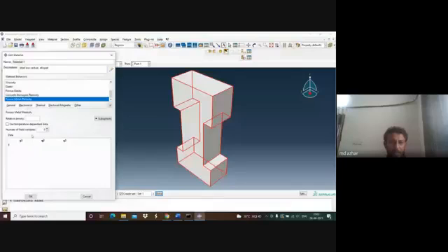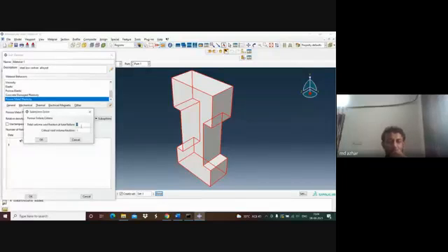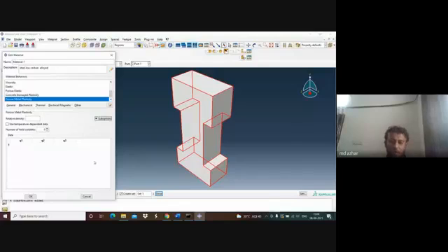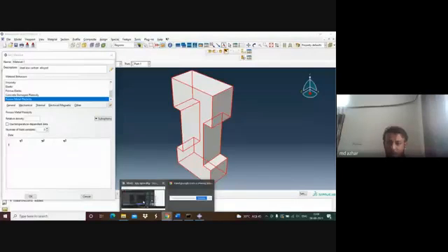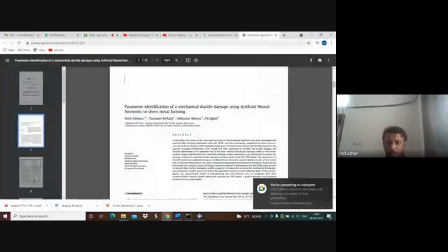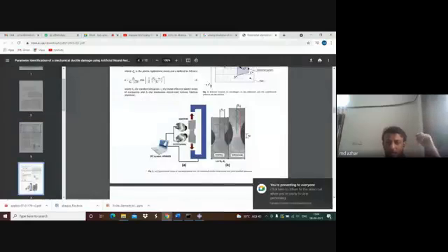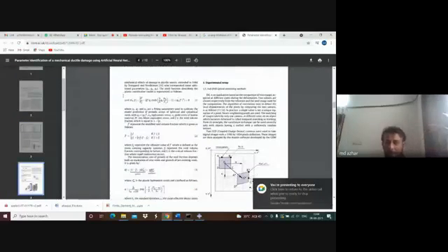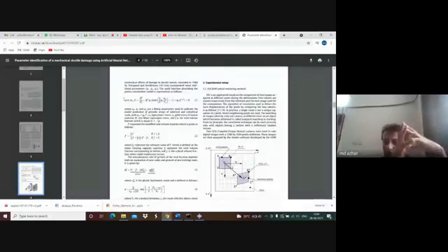So in porous metal plasticity, you'll have Q1, Q2, Q3. This is based on the ductile model, which you have to understand. And then you'll have the porous failure criteria. There you'll put some of the failure criteria. So there's one GTN model. If you study it, this is just one example of a model I am giving you so that you understand it. But similarly, there are many mathematical models.